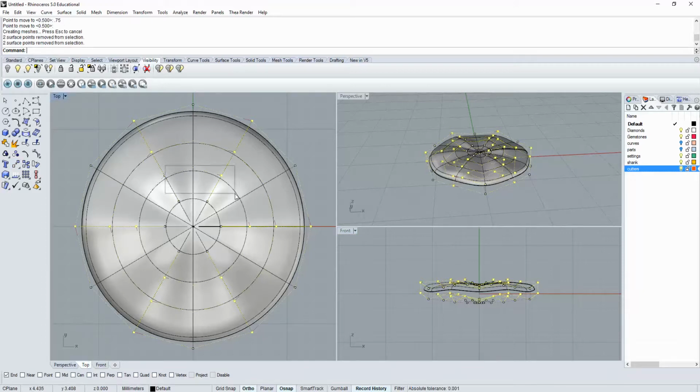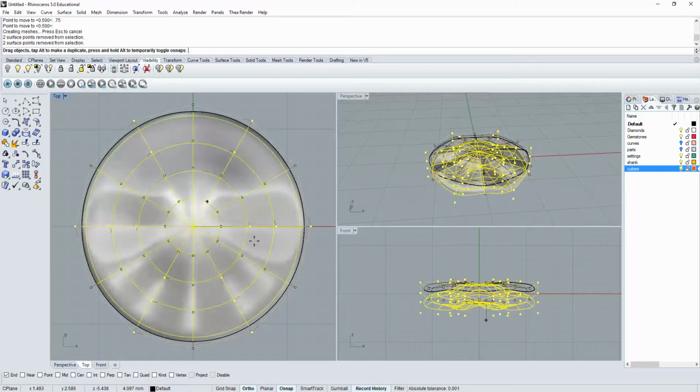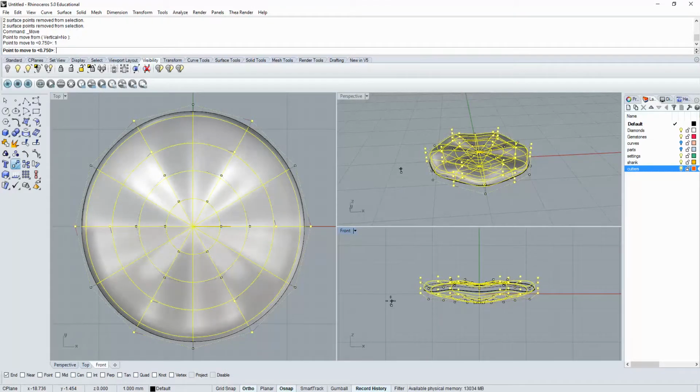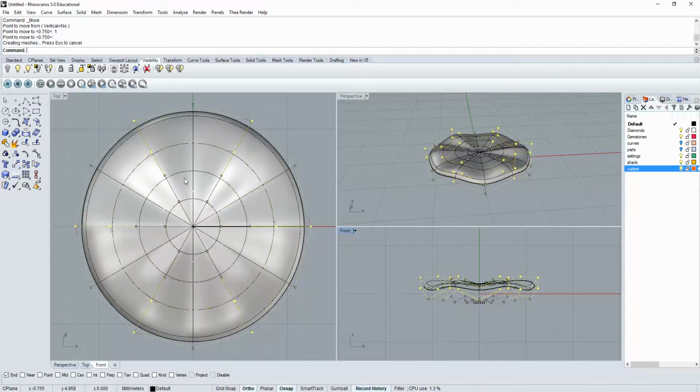And you could also create this kind of thing. Oops, don't move. I didn't want to do that. You could also create this kind of thing using like a rail revolve to create a wavy surface. I wanted a nice simple surface, which is why I think this works well, but there's lots of ways to create a wavy surface, thinking about where your ISO curves will be so that you can do your pave layout afterwards. So I'm going to move this again using the move button. And this time I'll do 1 millimeter, and then I'll deselect.